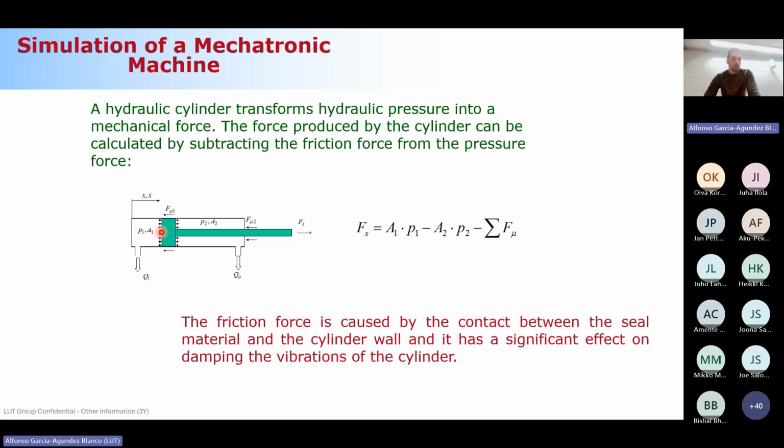A force is just the area times the pressure, okay? In terms of unit, if you want to understand it. Exactly, pressure times area. Remember, pressure is Pascal. A Pascal is Newton divided by a square meter, no? So, Pascals, pressure times area, square meters, provides newtons, okay? Which is force. So that is why I have on this side A1 times P1, a force coming from this